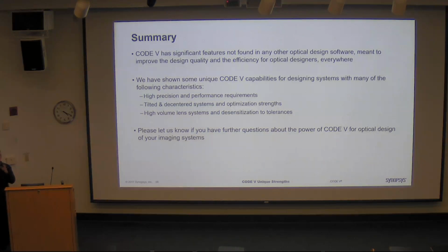Essentially, I'll explain what it does, and then hopefully that will answer the question. With this very fast tolerancing method that we have, we know how changes to the exit pupil function affect a subset of performance metrics, such as RMS wavefront error or diffraction MTF. So what the alignment option does is that you set up a model in CODE V that represents your optical system perfectly aligned, in the configuration however you're getting your interferogram, your as-measured configuration, which may be different than your as-used configuration.